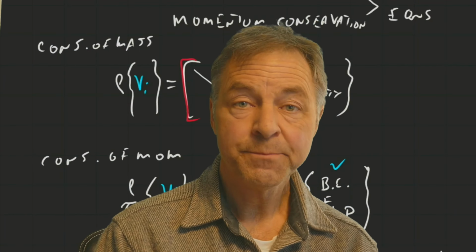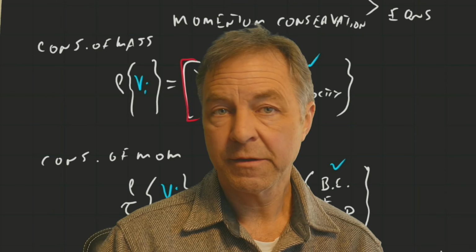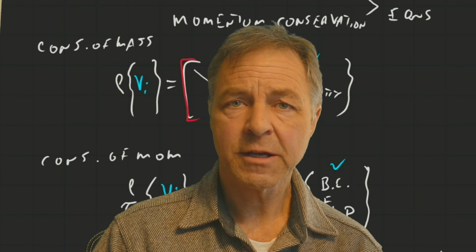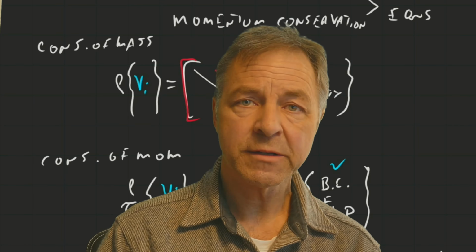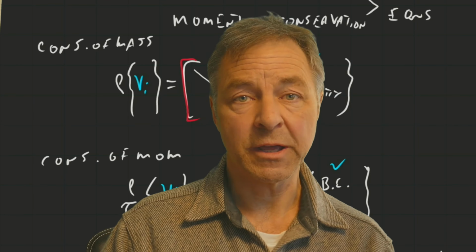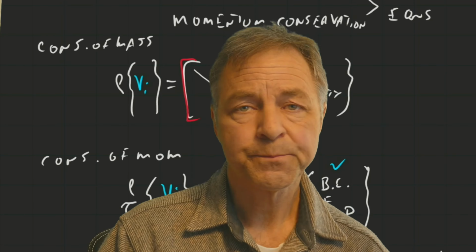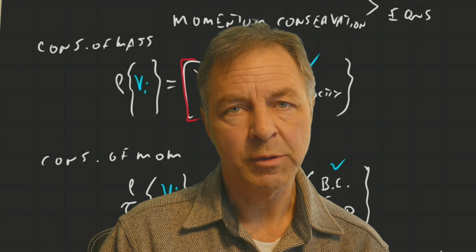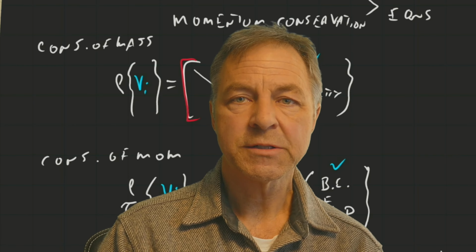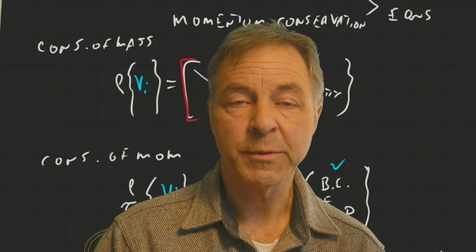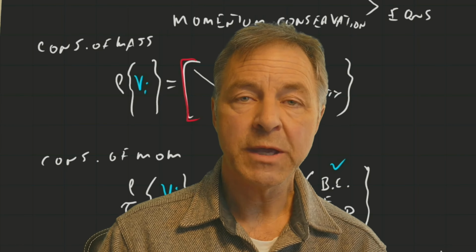We've run a study, we've run a simulation. We found that the simulation in the first cut didn't come up with the same lift to drag coefficient ratio that we expected. We were expecting a ratio of something like 40, and we got something like 4. So clearly we have a problem. So let's look more carefully at this simulation approach and see what we can learn from it, and then see if we can change the simulation parameters to make it more realistic.